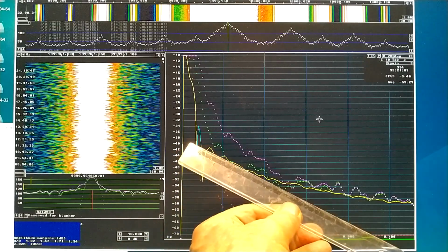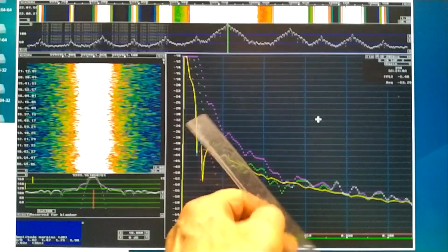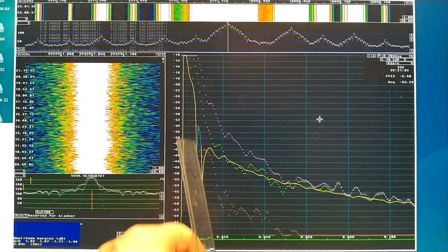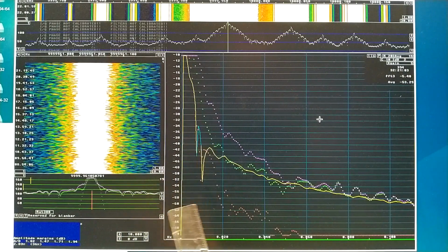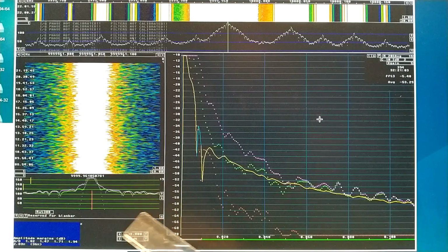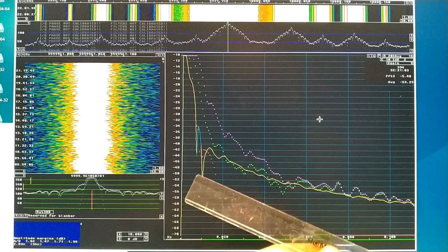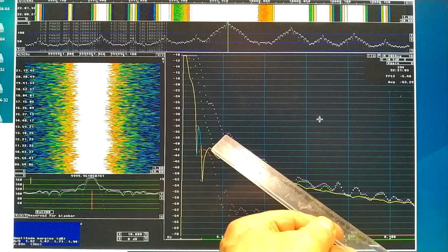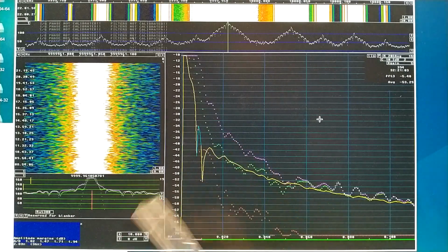But I can guess the curve would look something like this, and I can see that channel 1 goes steeply upwards below 0.15 or maybe 0.2. So a phase locking to the rubidium with a corner frequency of 0.02 Hz would probably be an optimum source for this kind of measurements. And then, of course, it would be nice to have the channel 2 oscillator improved before locking it.